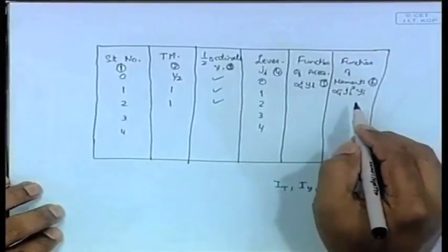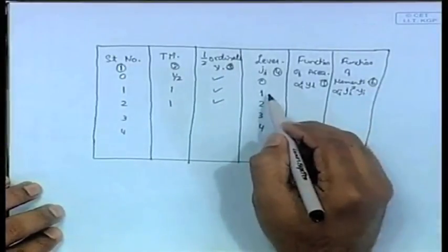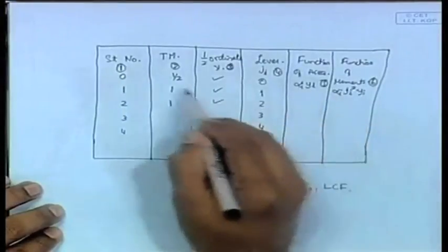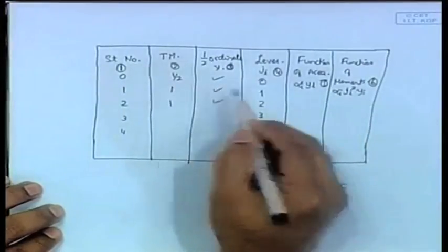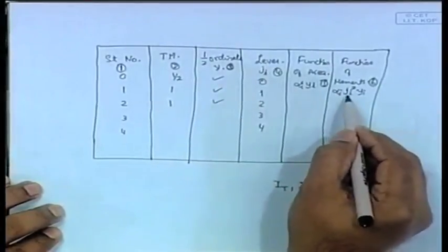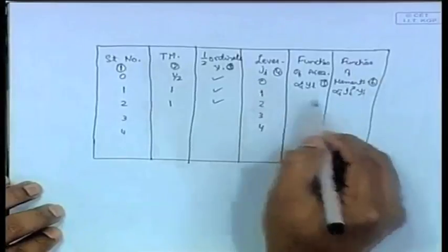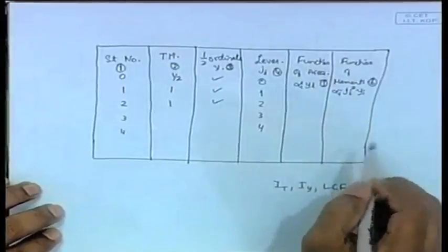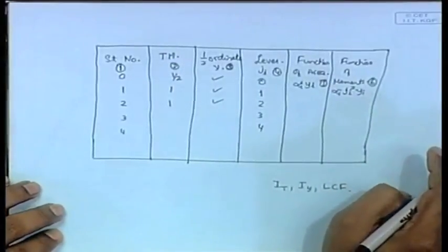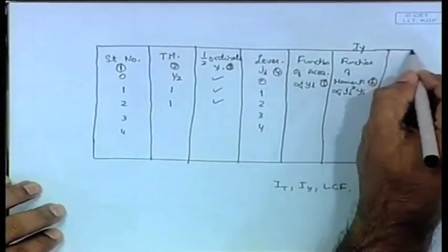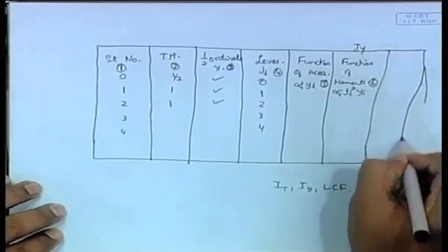So, what are we doing? Column 6 will be, you have j I, you square j I, you multiply it with the area, you multiply it with the half ordinate. Alpha I is this column, j I is this lever column squared, y I is this half ordinate column. Multiplying them will give you another column of the function of moments. Note that this is to calculate I y. Then we need another column.